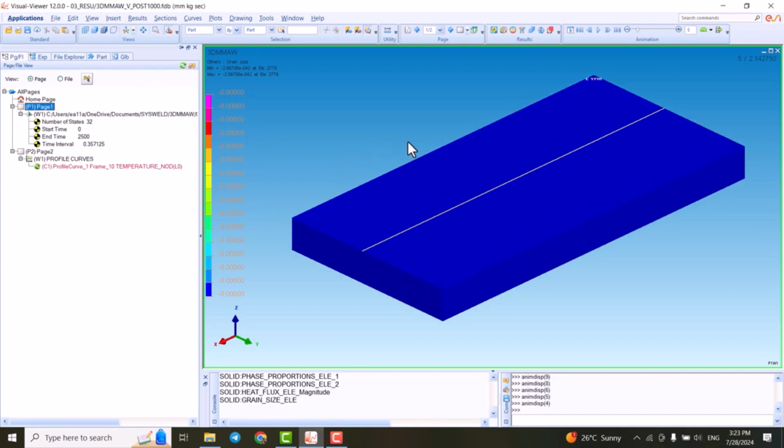So we did the thermal analysis of a 316L stainless steel in 3D. The objective of this video was to do the calculation in a 3D model, so it's important to know and set the parameters. If you check the results and see there is any residual material left, we can go back and do the analysis again. Or if you want to make it perfect, you can select other parameters and see what happens. If we go with higher speed or lower speed, you get a really good understanding of the welding process you're working with.